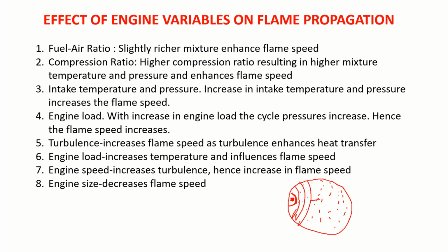This is what I call the flame speed, V. As it travels, it consumes the charge and the pressure rise will increase. So you have passed the spark, the flame front appears, then the pressure rises. This is what really happens as it travels and travels.